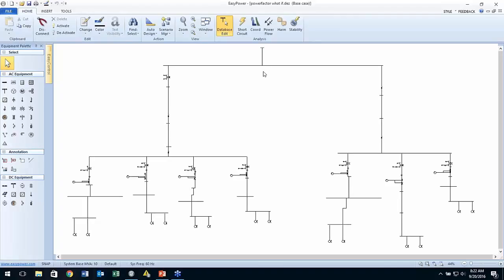And so one of the questions that came up is, well, what's the cost of the power factor correction compared to the penalties that we may be getting from the utility? I think that's a valid question, and I'm not the person to ask. The other question that may be asked is, are there alternatives to deal with the power factor correction, and by adding all this capacitance, what have we done to the harmonic sensitivity of the system?